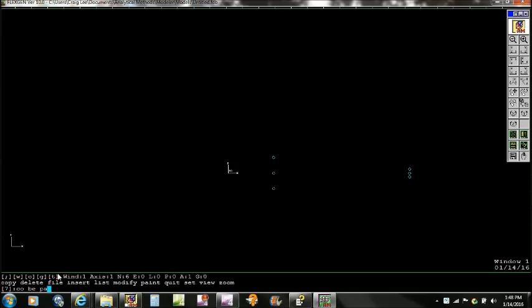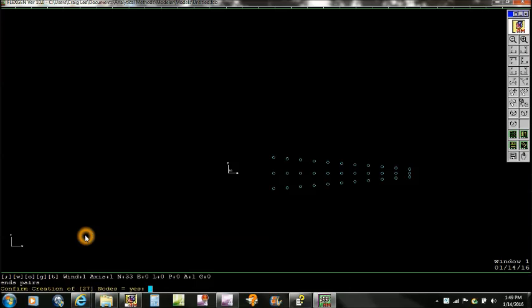Now we want to do copy between pairs, and we'll identify the pairs that we're going to copy between, and we're going to insert 9 sets of nodes in between there, and we're going to go equidistant there. They'll be evenly spaced. We'll hit that and say yes, we want to create 27 nodes. So that forms what the cross section of one of the disks will be.